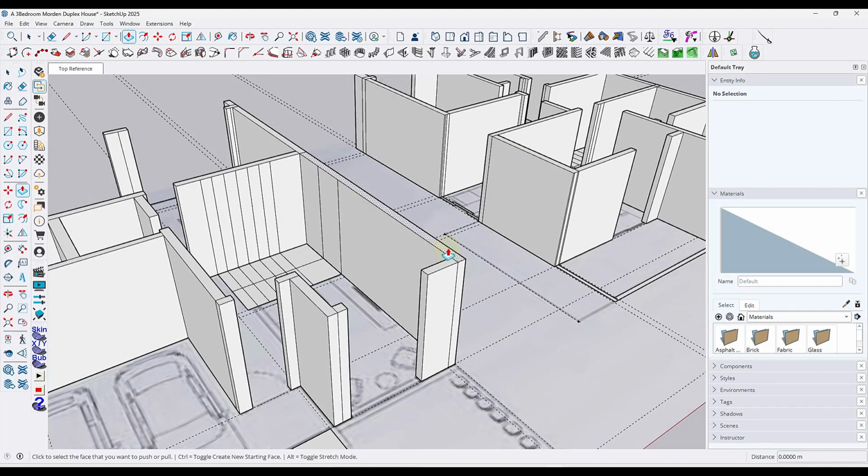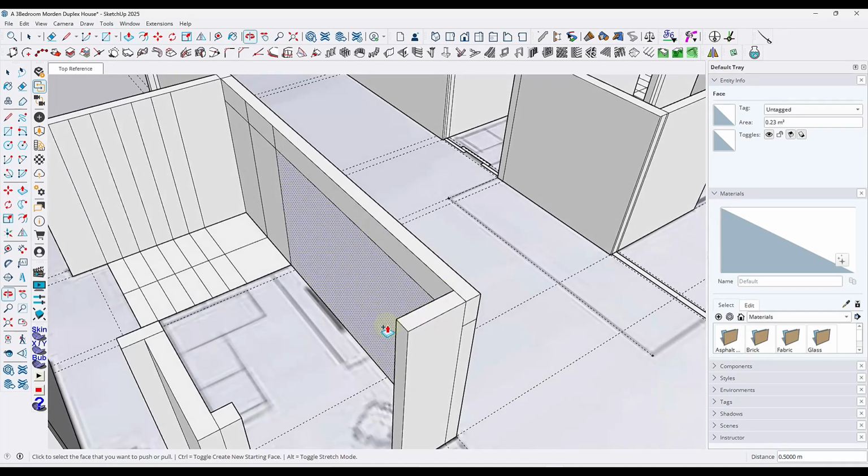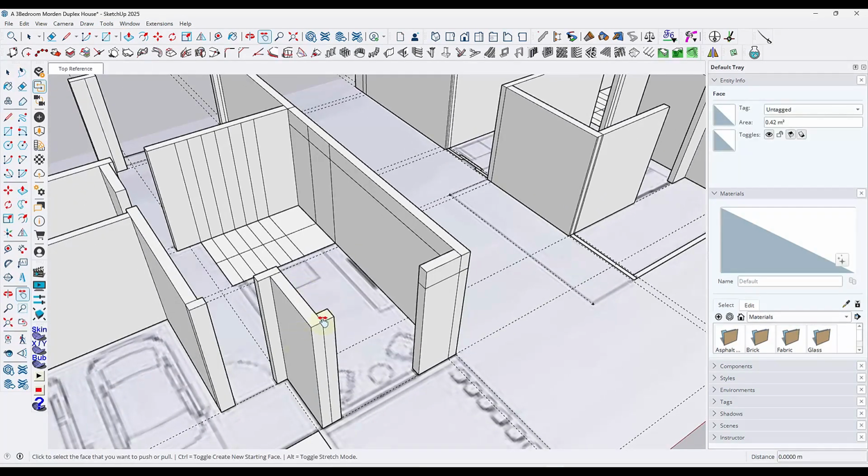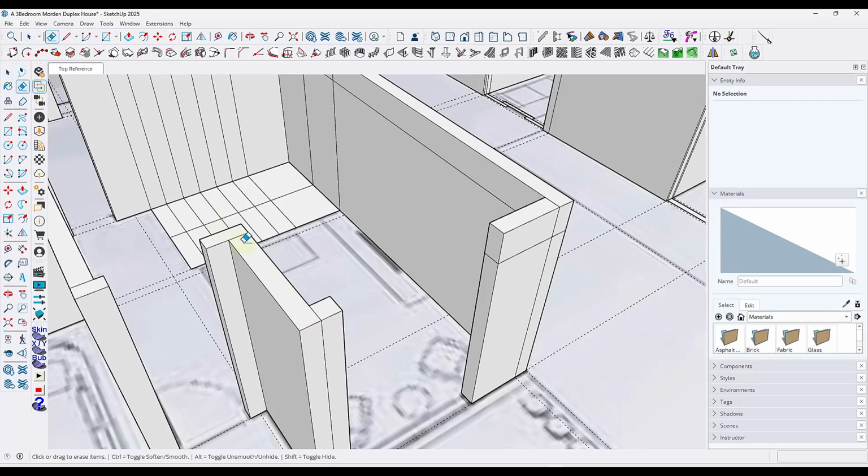Okay, so use the push pull tool, press Control first of all, then click down, and you can use 0.5. 0.5 is okay. So we're going to do that with the plus icon still selected, so all the building. Alright, the best way to achieve this, press Ctrl Z, so you can delete this space to do that together.